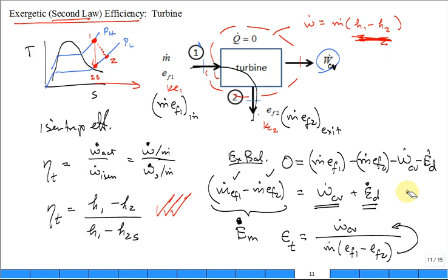What could the highest or the greatest second law efficiency be for a turbine? Could it go over 100%? No, it's not going to go over 100%. But it could come up to 100%. Make sense? What are typical numbers? They're very close numerically to the isentropic efficiency, but they won't be spot on. So maybe it'll be 92%, 85%, 75%, somewhere. Okay.